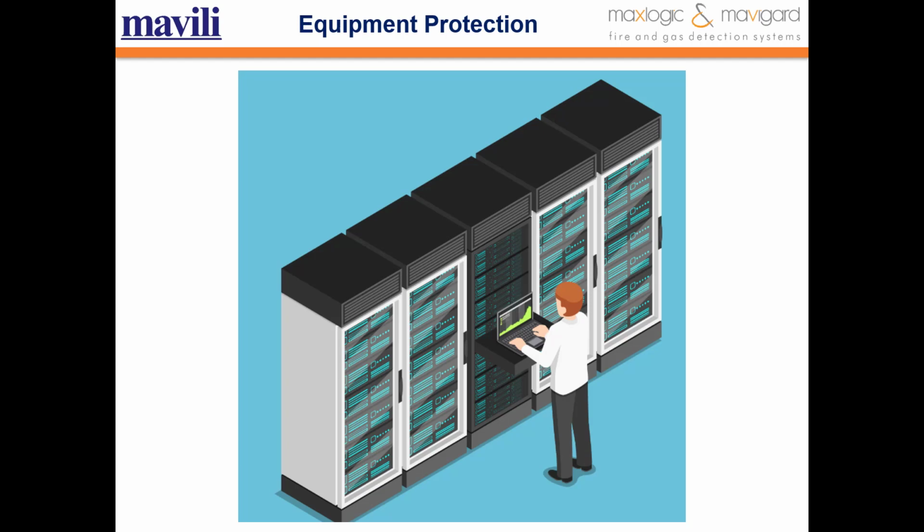The following gaps: first, those with a fire load density of no more than 25 megajoules per square meter of combustible material. And second, those containing cables related to the emergency system with a fire load density of no more than 15 megajoules per square meter of combustible material. Independent detector protection is not required.